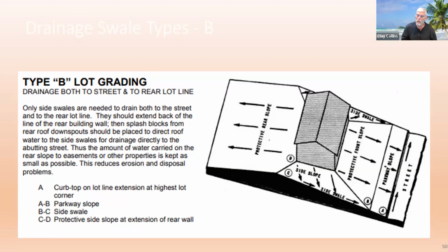The SOP requires that you inspect grading and drainage, and there is no differentiation between the first 10 feet and the second 10 feet. What you're looking for is the impact on the house. And that impact can be caused by something that's 20 foot away. So no distinction.